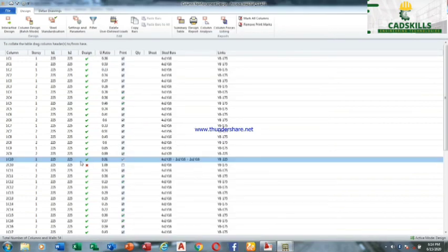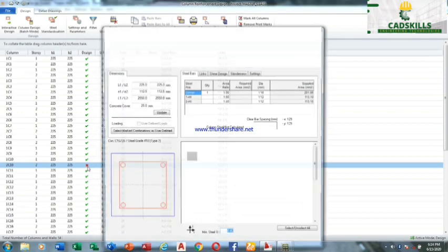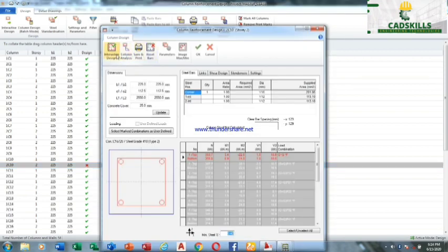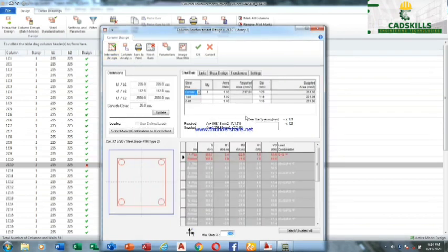So it will change. I mean the load that is coming to that beam is much. You see it. What did it give us? Oh, too much. You can choose Y16 and see. Oh, it's too much. Okay, make it Y20.